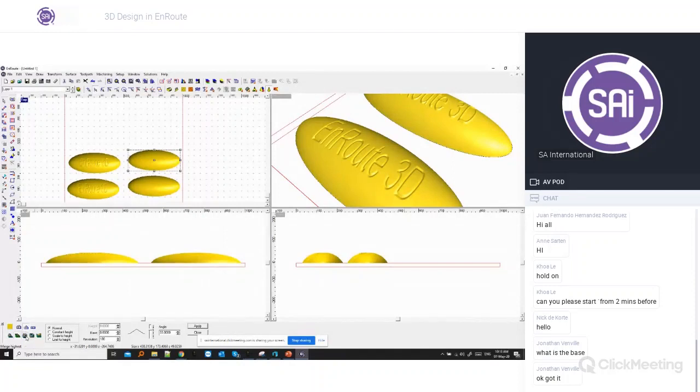If you choose merge highest, then it will only add to the relief if the points in the relief that we're adding to it are higher. So I will just add a base of, let's say, 50 to this.